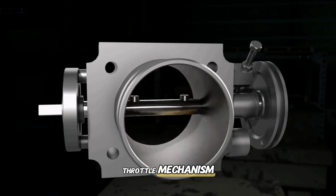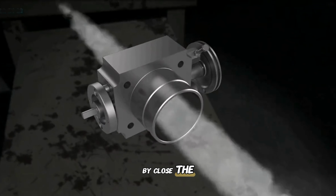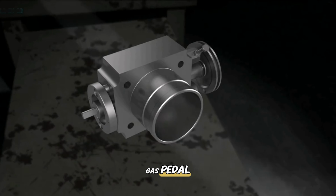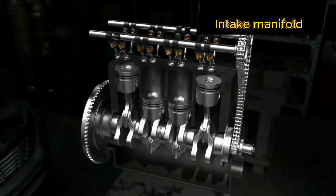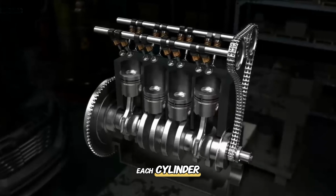This is the throttle mechanism. There's a throttle body. The throttle valve can be opened or closed to control the amount of air inhaled. By depressing the gas pedal, the valve can be opened to allow more air to enter. This will increase power and speed. The mixture passes through the intake pipe, evenly distributed to each cylinder.